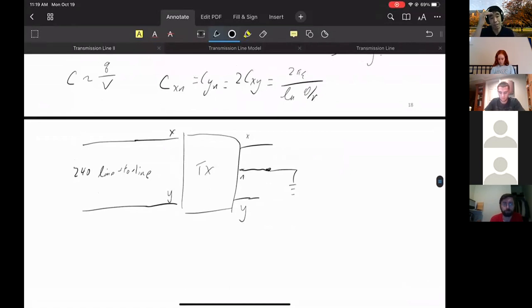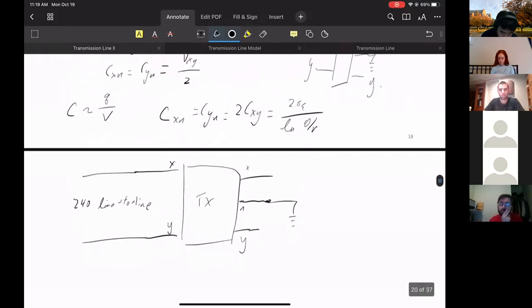You have this transformer. You can think of all it does is add a third wire as a center tap, the third wire. So we have a reference. We just reference to this neutral. So if you have a 120 circuit, let's say you have a load. So your load is 120. You connect like this.